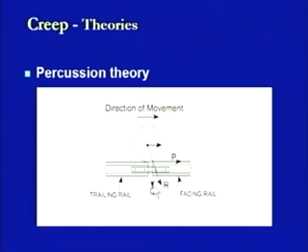Then in this case, this component P will try to move this rail section in the forward direction. So, this trailing rail section will try to remain at the same location, whereas this rail section will start moving in this direction. So, if this is what is happening, then obviously this joint will start getting open, because this will remain at this location, this is moving forward. So, this is what is termed as the opening of the joint.